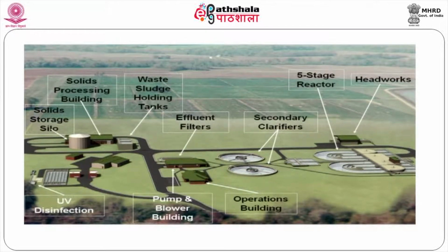In conventional systems, we are keeping microbial mass only up to a maximum of 12 days. Here we are keeping 20 or even 25. For some industrial applications, we are keeping microbial mass for 48 days. So, that is why we can partly stabilize the microbial mass.